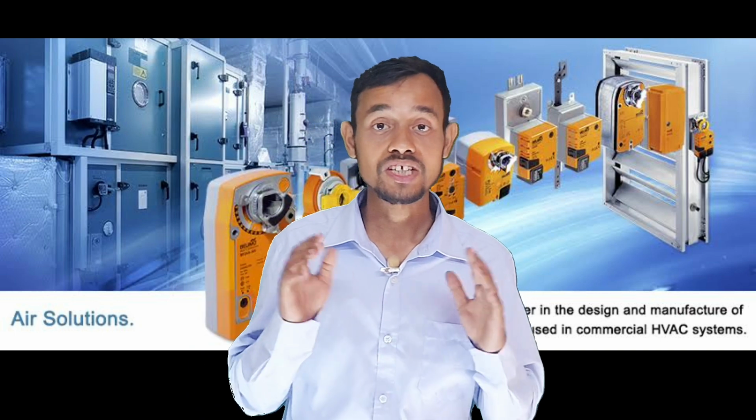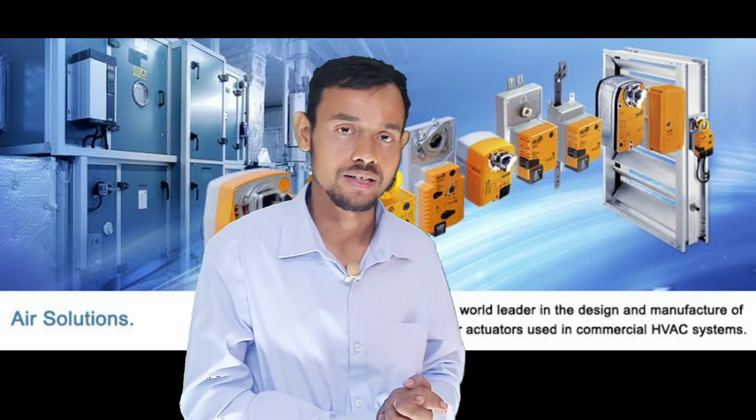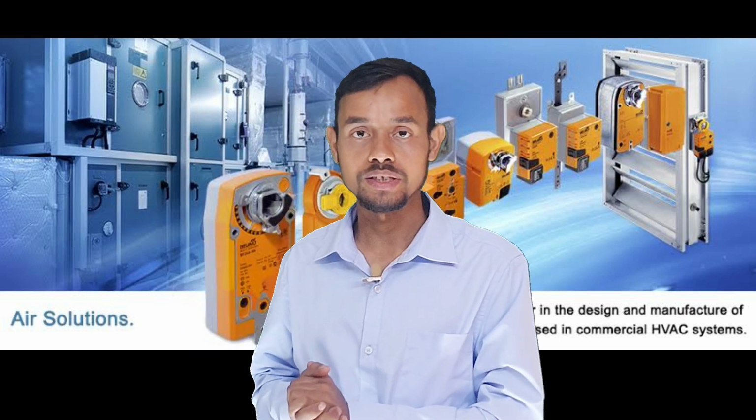Next is makeup air. What is makeup air and how does it work? So let's get started. The makeup air unit, MAU, is a type of air handling unit which only circulates fresh outdoor air. There is no recirculating of indoor air. MAU exhaust fans are used in rooms like kitchens and bathrooms to suck the air from inside the building, because the building is tightly sealed.